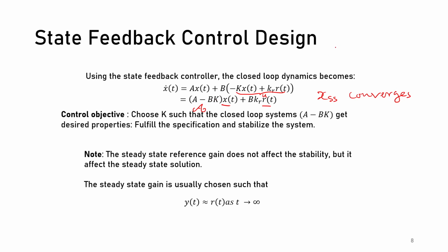Let's see just first order, as an analogy. We will expand the first order to high order, but let's see first order first. Let's say you have just h dot equal to minus 2h plus a constant or step, let's say just 2 as well. Do you think this system converges? I mean, H converges? Look at the homogeneous solution.